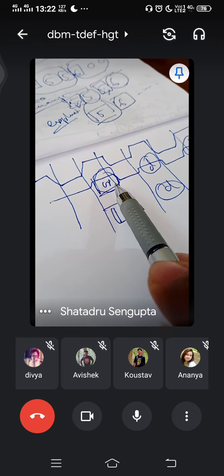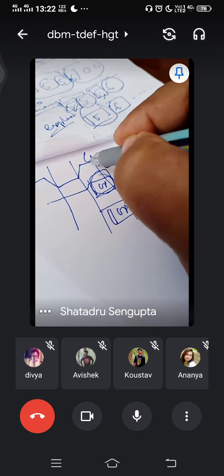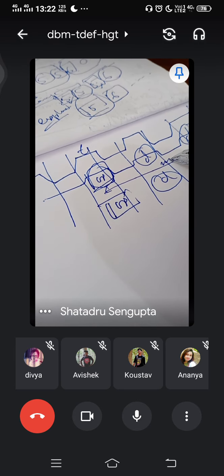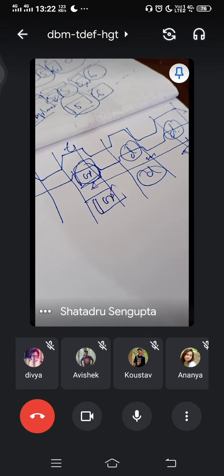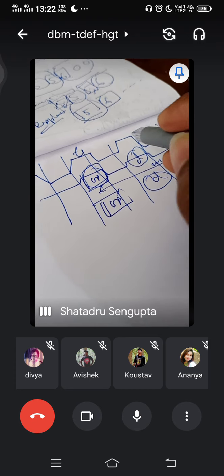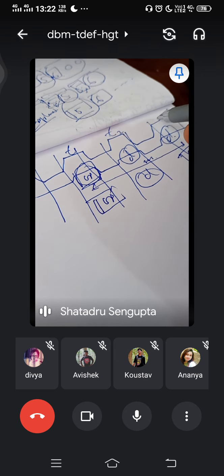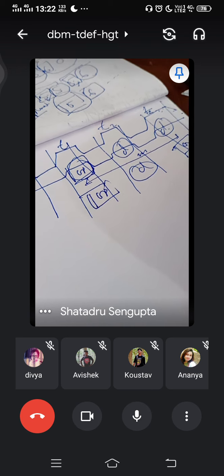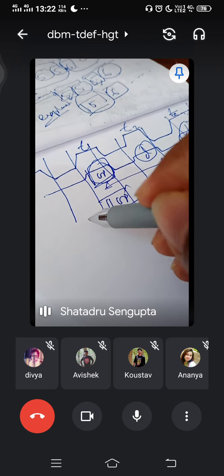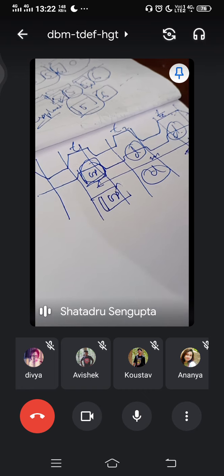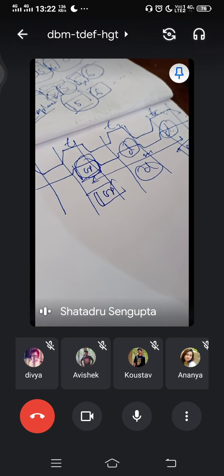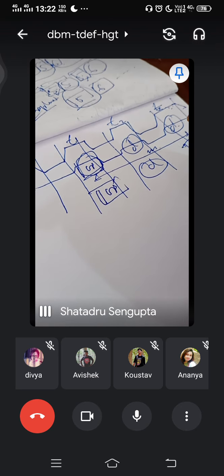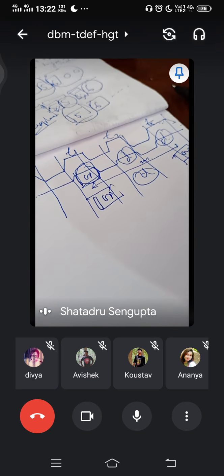First clock pulse, okay. So these are T cycles, and this is one machine cycle called M. Clock cycles are called T. So T1, T2, T3, etc. Machine cycles are called M. The first machine cycle is shown. There are other signals that can happen simultaneously with the clock, and they will be timed. So this timing is very important. No clock, unfortunately, and the total thing will go into disarray.